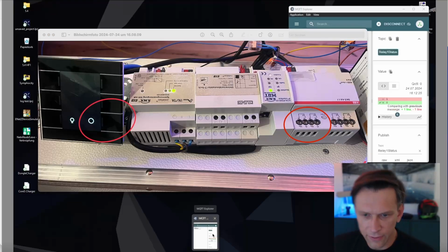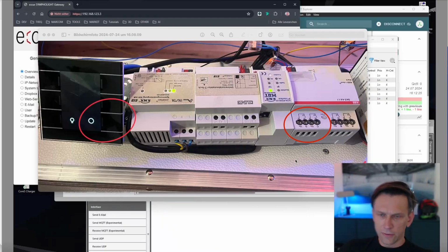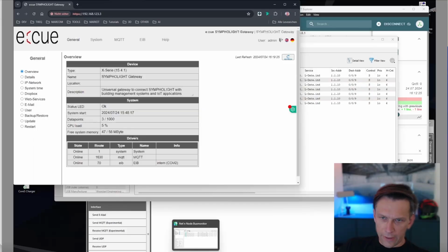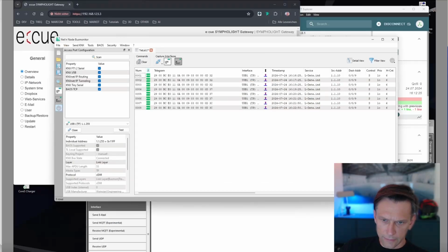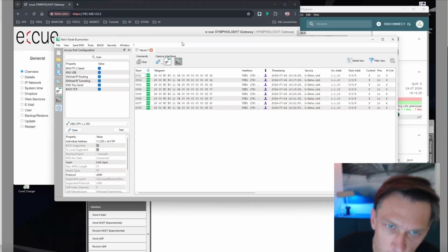There are different kinds of monitoring options for the KNX bus. I have here a small device from Weinzierl. It's connected via USB to my PC, and it monitors the KNX bus. Besides this, the touch device also provides the current temperature. There's a temperature sensor inside of the wall mount touch interface. Have a look into the software called Net'n Node Bus Monitor.